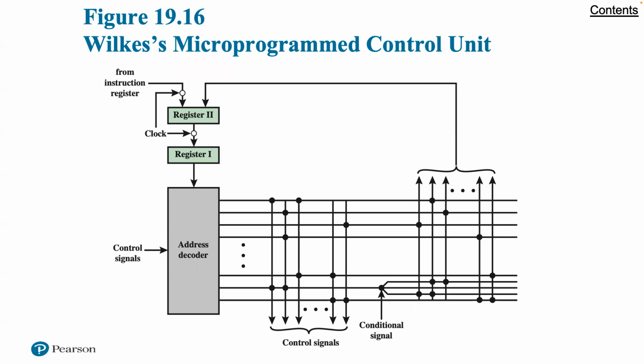The heart of the system is a matrix partially filled with diodes. During a machine cycle, one row of the matrix is activated with pulses. This generates signals at those points where a diode is present, indicated by a dot in the diagram. The first part of the row generates a control signal that controls the operation of the processor. The second part generates the address of the row to be pulsed in the next machine cycle. Thus, each row of the matrix is one microinstruction, and the layout of the matrix is the control memory.